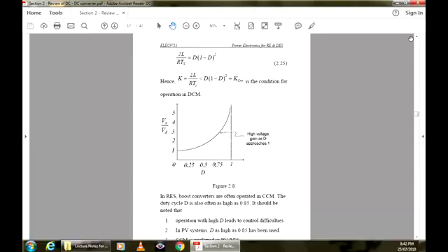Because of that, power supply industries operate boost converters in discontinuous conduction mode, which will be somewhere here. So the relationship would be linear. Even with D equal to 0.5, if we operate at discontinuous conduction, the voltage change from there to there would be a reasonable change of voltage for a reasonable change of D. That would be the case with discontinuous conduction.